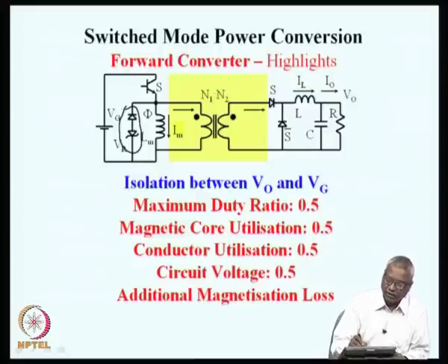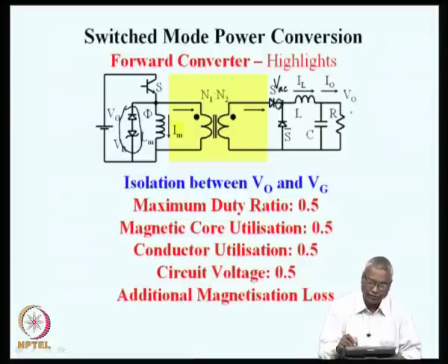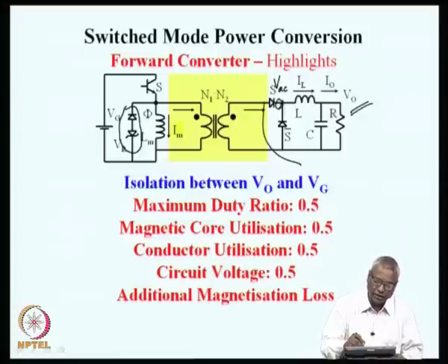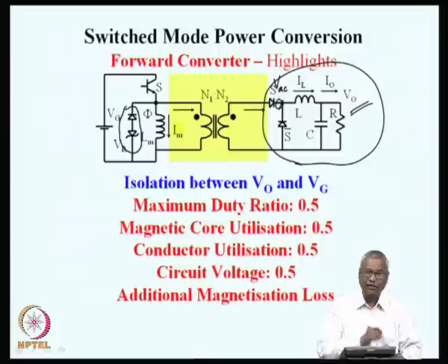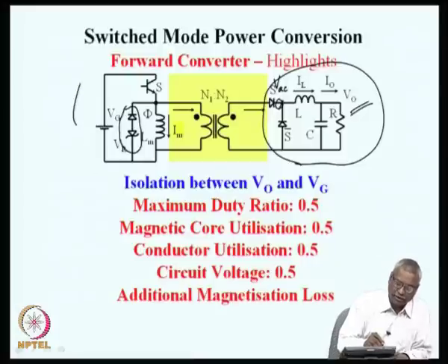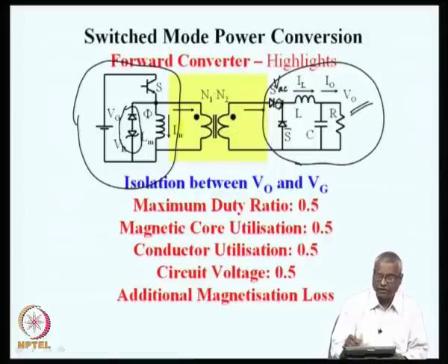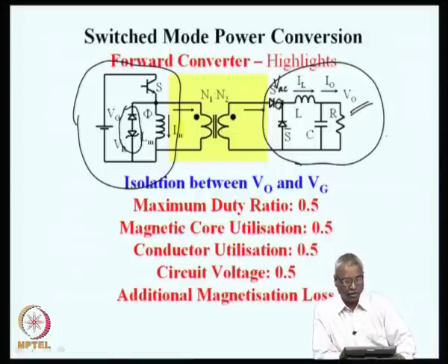And the secondary side voltage, which we notice on this side, an AC switching voltage, is then filtered through the inductor L and C, and we provide V naught at the output. The secondary part is identical to our standard non-isolated buck converter. The primary switch ensures that energy is transferred to the transformer primary, and then from the secondary side this energy is transferred to the load.